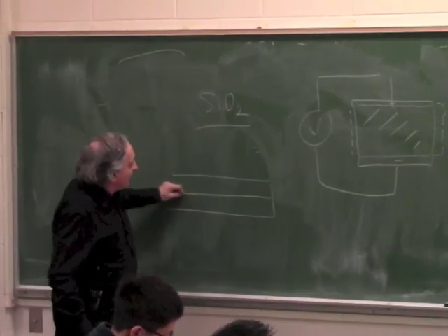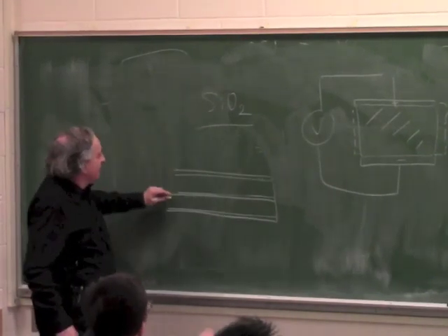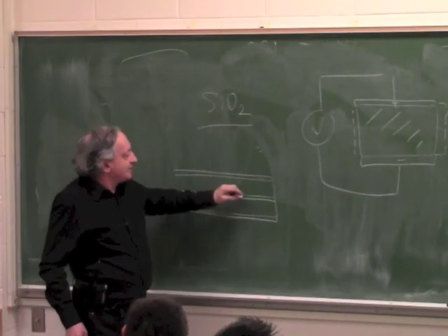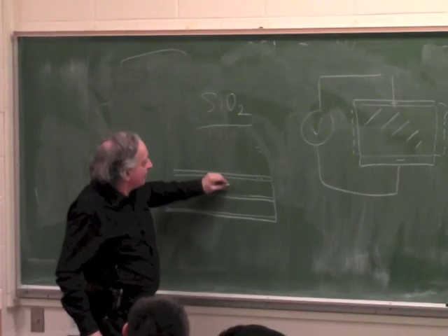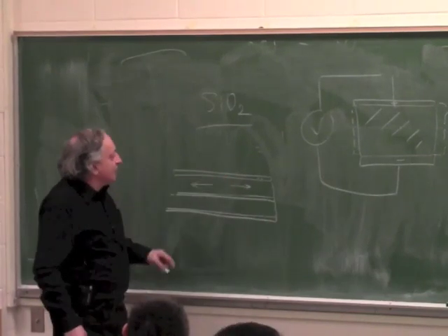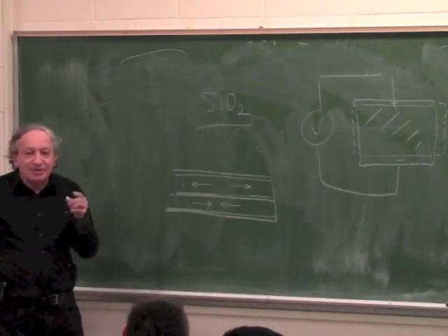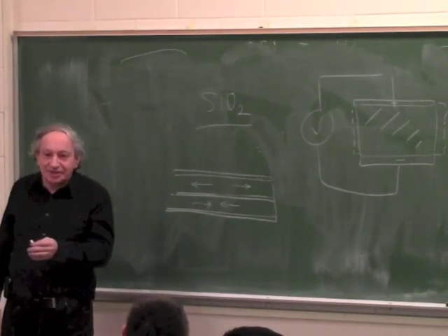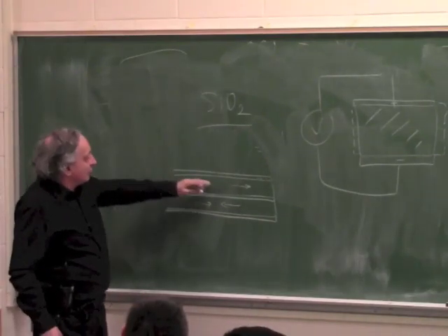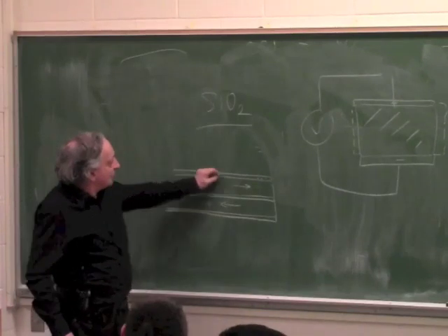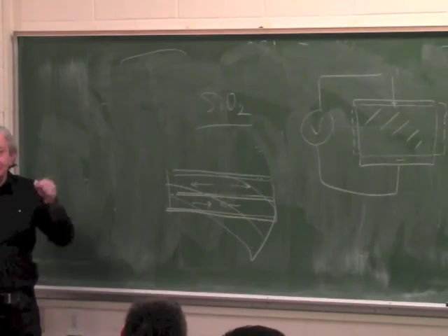and make it from 2 layers, so these are the electrodes. This is a material which expands with voltage. Then you have a second material which shrinks with voltage. It could be the same material, just cut in a different direction of the crystal. Because now, when you put a voltage on it, the top will expand, the bottom will shrink, and the whole thing will bend. Just like a bimetallic thermostat.